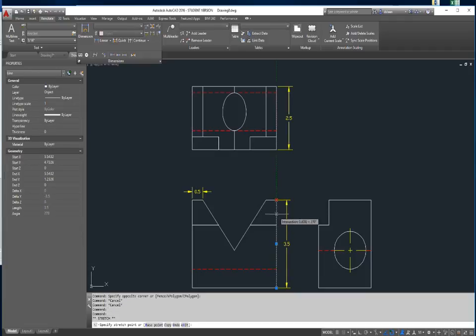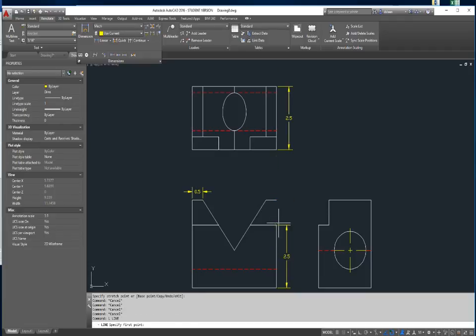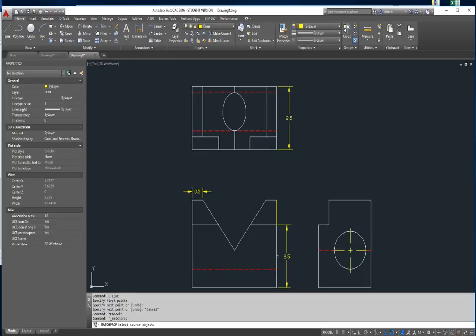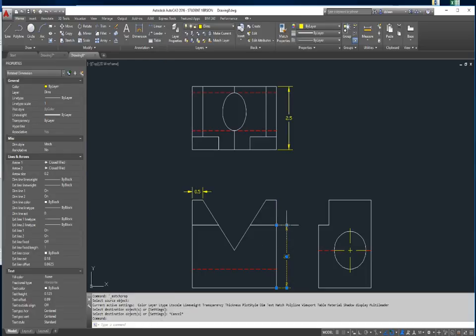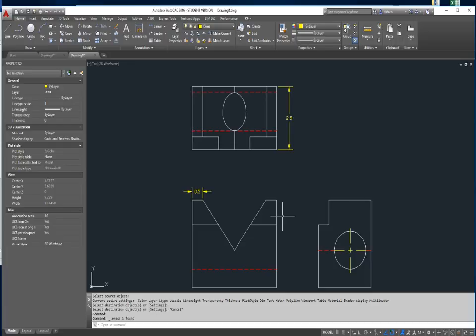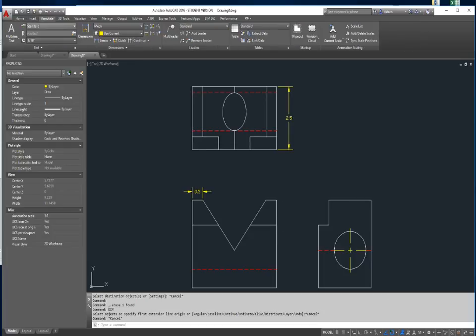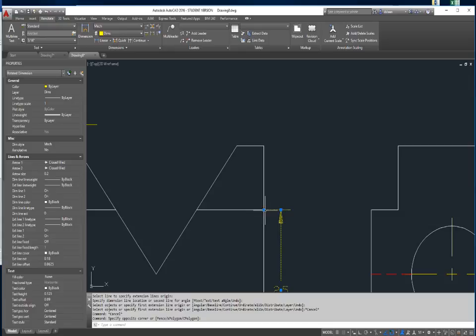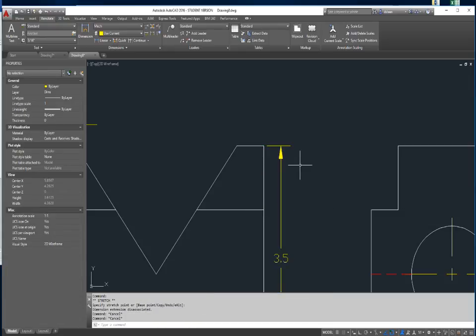If you have something that looks like this, where you have two lines, and you're just looking at your drawing, you can see that I just created two different lines there. But if you created your drawing like this, and you do a dimension vertical or a linear dimension, and you just select that, it's not going to go all the way to the top. So how can you edit that? You can click on it, move that node to that endpoint, and it's that easy.